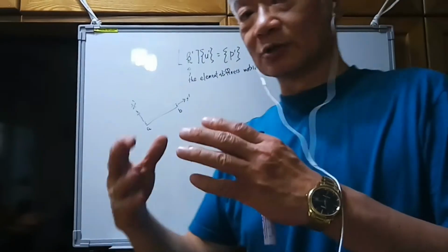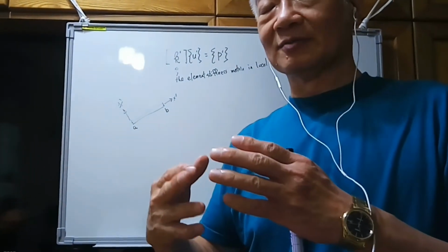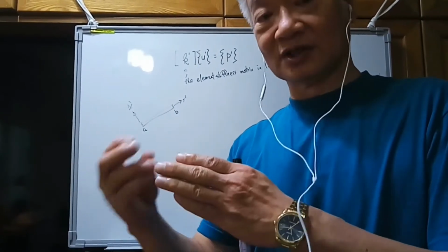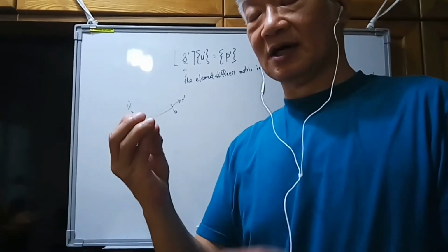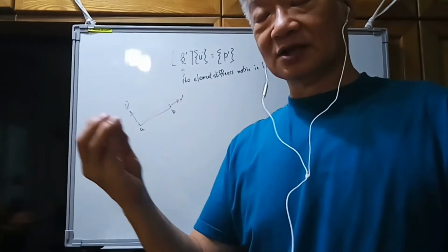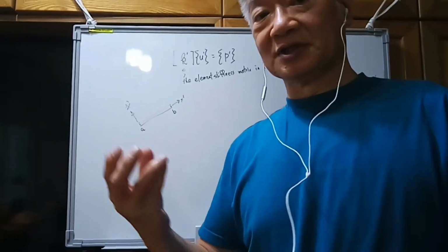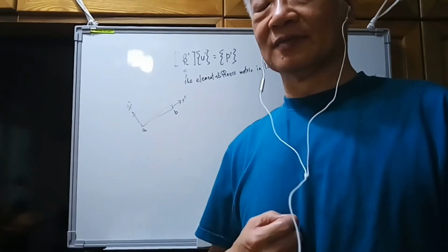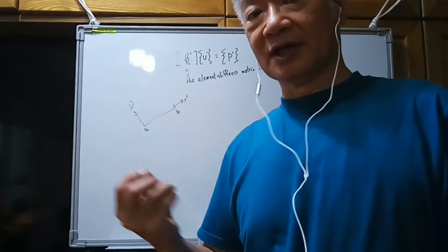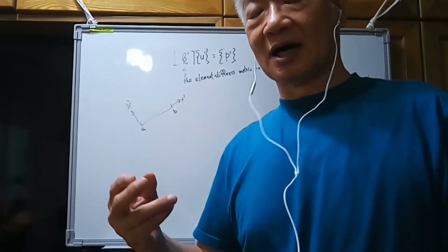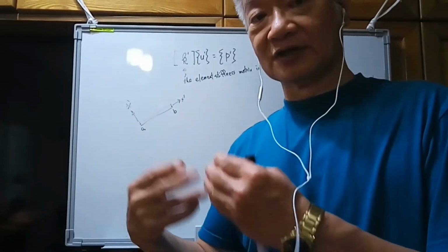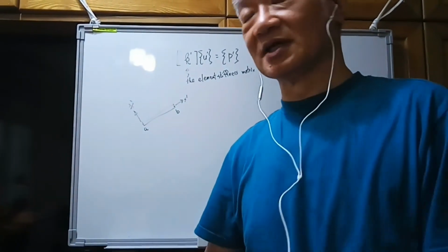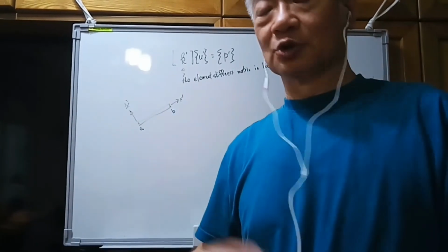But later we need to assemble the element stiffness matrices at the same joint, since the two end joints are usually connected to not only one element. For the two end joints, usually two or three or even more elements are connected to the same joint.